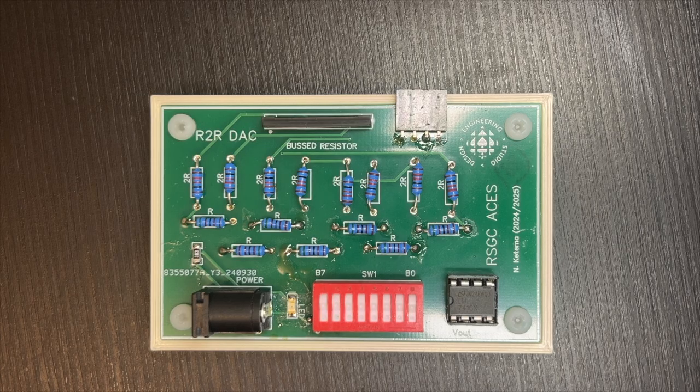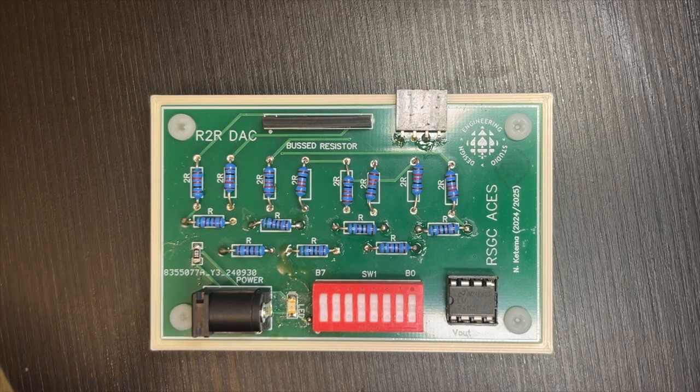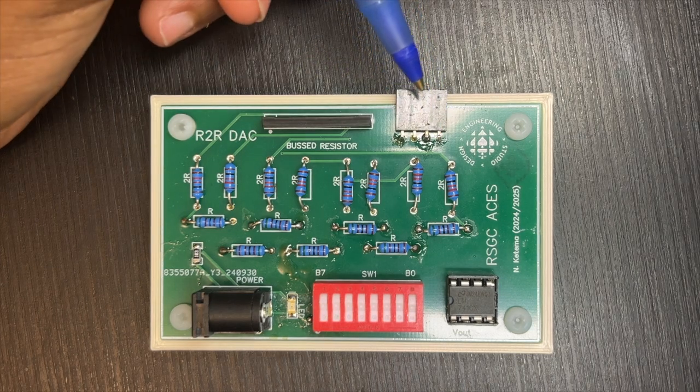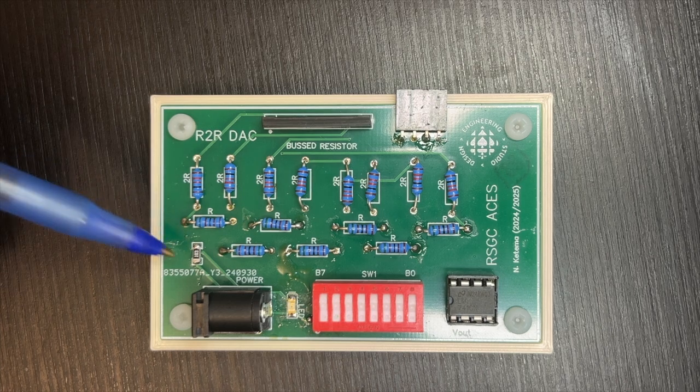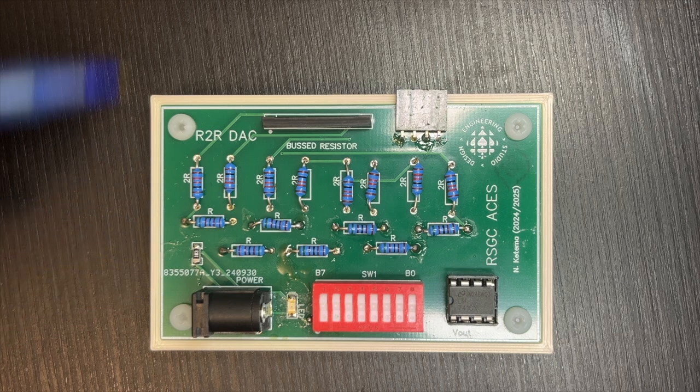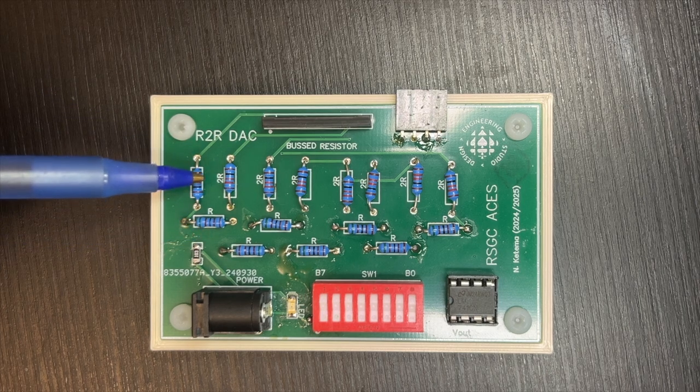Although not functioning, the printed circuit board prototype of the R2R DAC uses a custom PCB, a 2.1mm DC power jack, an op-amp chip seat, a 4-position header right angle that is through hole, a surface mount yellow LED, a surface mount 103 capacitor, a bus resistor, 4 screws, 4 brass inserts, and the 2 sets of fixed resistors, the 5.1K ohm fixed resistors and the 10.2K ohm fixed resistors.